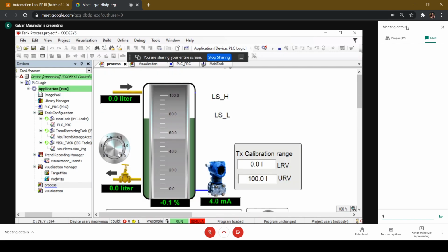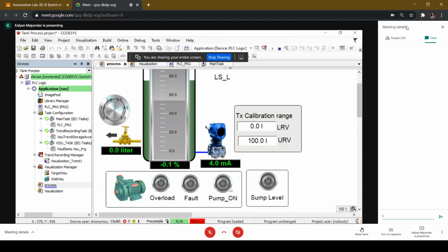So this is just running, and this is my outflow rate maximum. My application, you could do it anything. 5 liter is the maximum possible. I'm turning this to 0. What that means is all my outlet valves are closed. There cannot be any outflow from this particular tank. So now I start my pump.